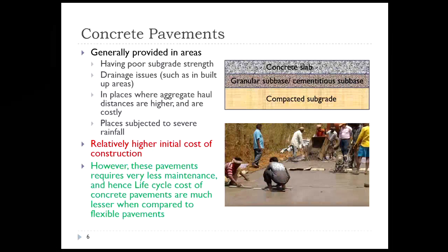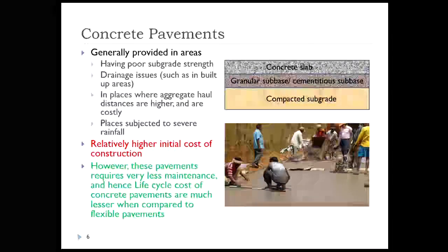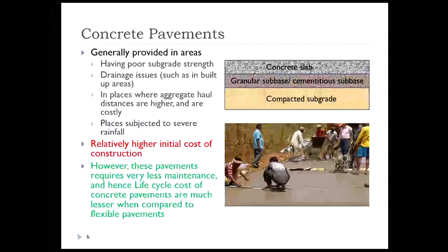So if you take a 20-year life cycle cost analysis period, your life cycle costs, inclusive of your initial costs, your maintenance and your residual value, you will find concrete pavements are much more economical when compared to flexible pavements. But most of the time, people are worried about the initial cost of construction.